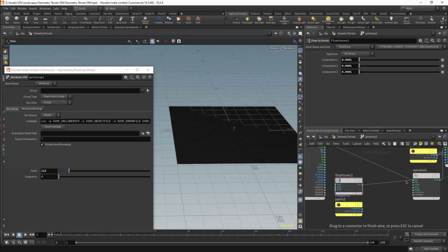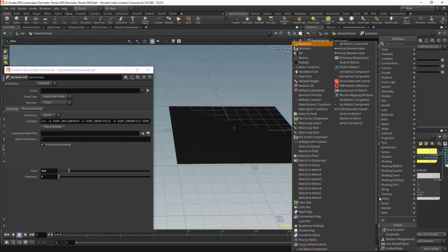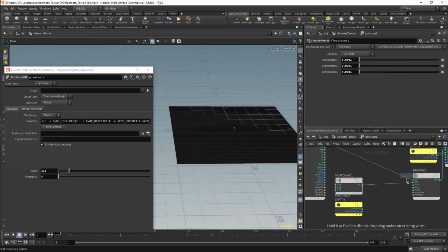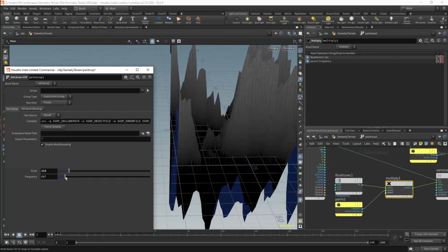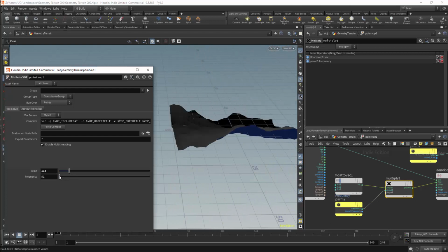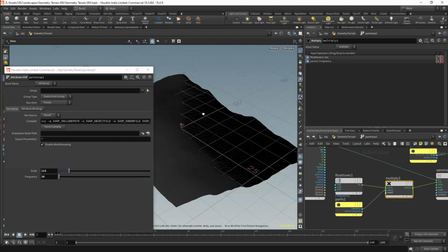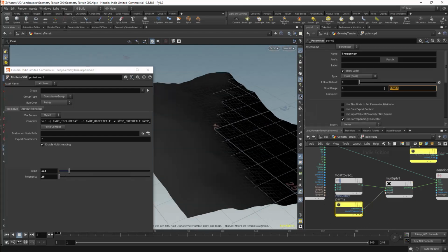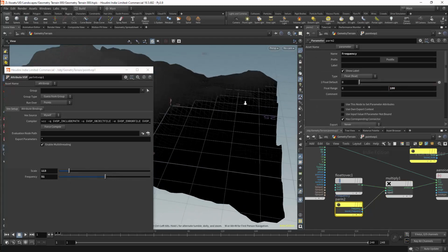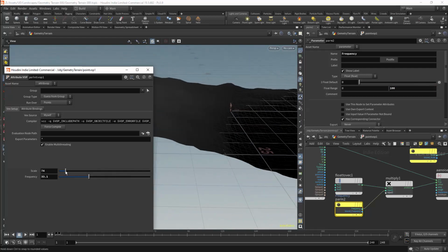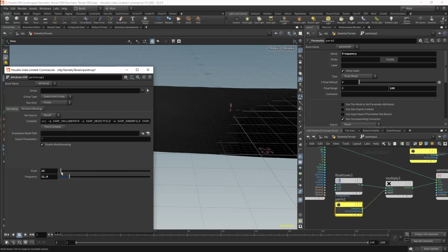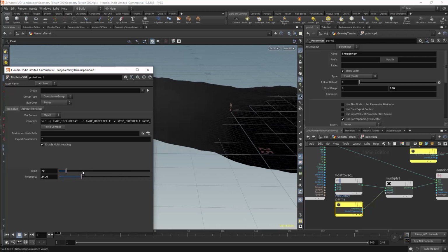This node will be connected to our frequency input in the noise node. We'll then get a multiply node, and we're going to multiply this value by our parameter. This should give us a bit more control over our frequency. I can then test this parameter. 1000 is probably a bit high for this parameter, so I'll limit it to 100 instead. We can now use this to give ourselves a basic landscape. This should allow us to make reasonably large-scale landscapes, but more importantly, it will allow us to make smaller landscapes, where I can test the finer details of my traversal system.